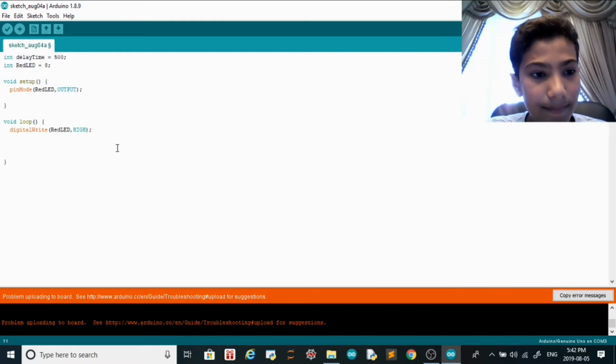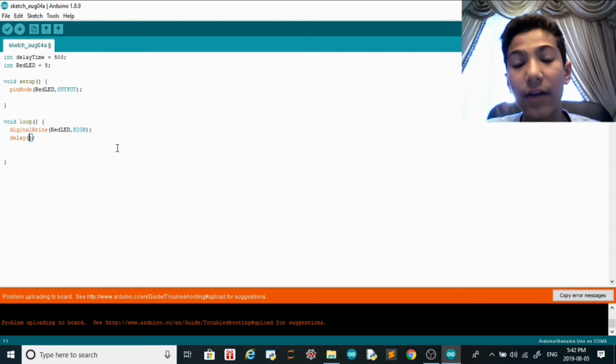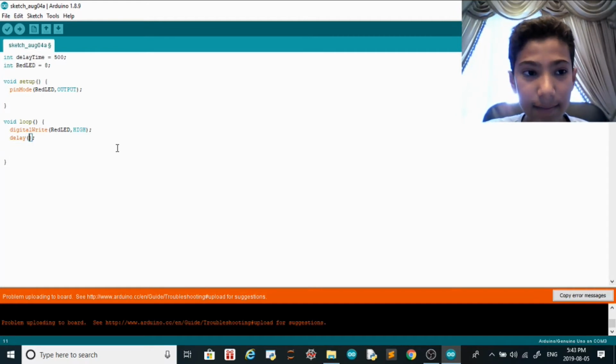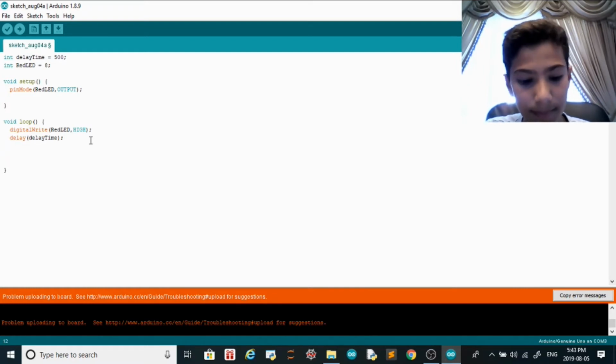And then we want to put a delay. So this is how you put a delay. And if you didn't have a variable for delay, you just put 500 or whatever you want. But I have a variable, so I'm going to put delay time, which is 500 milliseconds. And we're just going to take this and put it one more time.